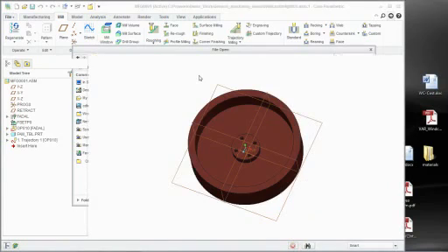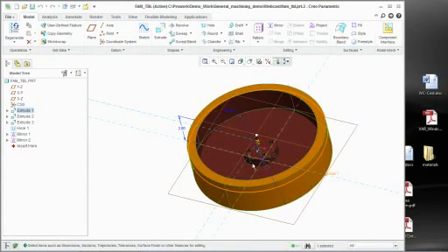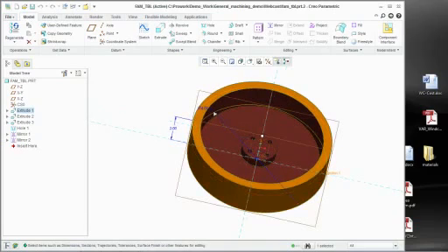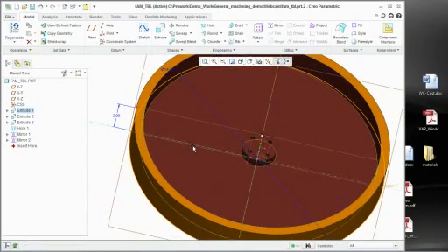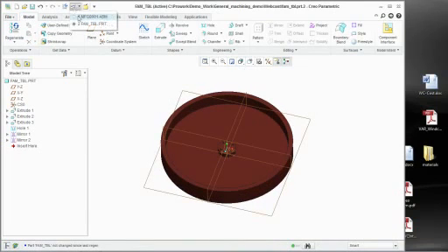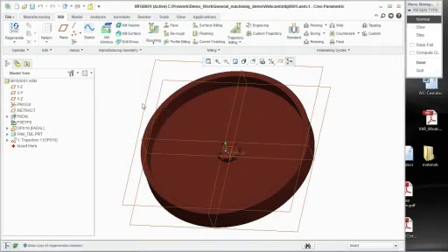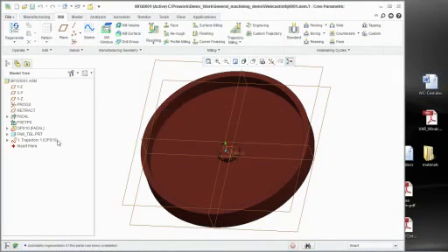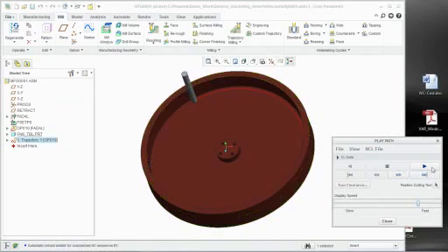And if I have a guy come in and say, instead of it being 8, I want it to be this big, okay, this big right here, I can go ahead and regenerate those changes. I come back to my machining file, and then all I have to do is regenerate all of my toolpaths. So now what happens is all of the toolpaths adapt to the new geometry. Okay?